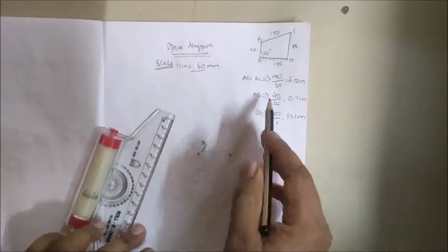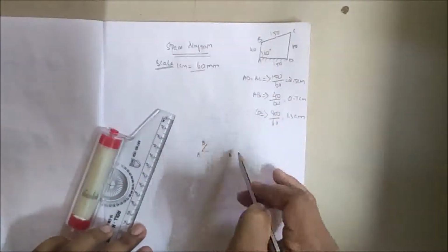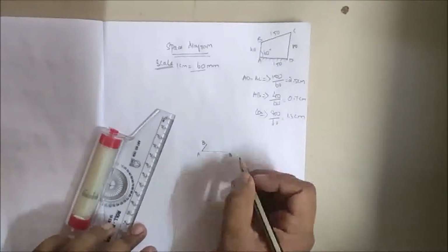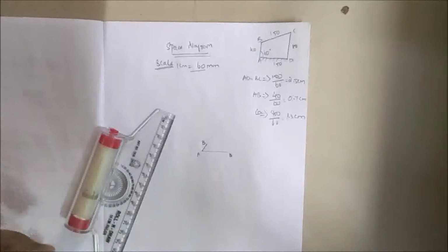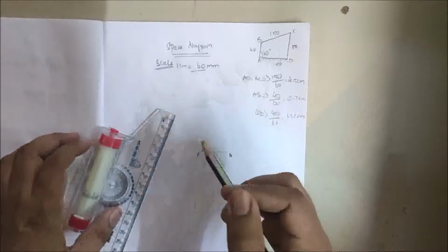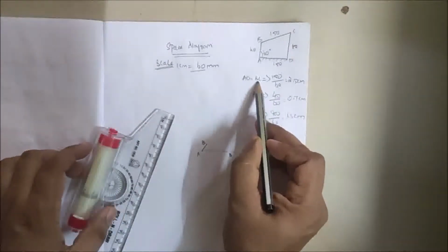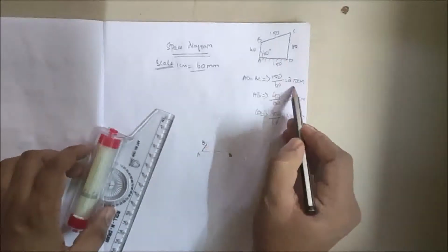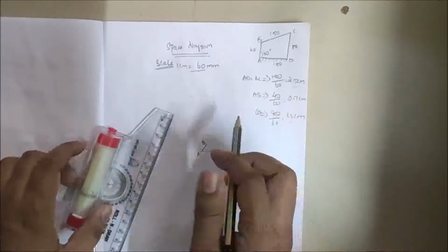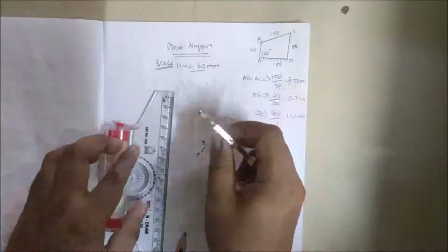So now as per our question, AB is found and D is drawn. So this is D. Earlier I drew it wrongly, it is AD. Next, we don't know where this point C is going to lie. So we have to think whether we can find it using the values we know. Now we know BC is 150 mm, that is 2.5 cm, and CD is 80 mm, that is 1.3 cm. So what you are going to do is take your compass with 2.5 cm as the radius.